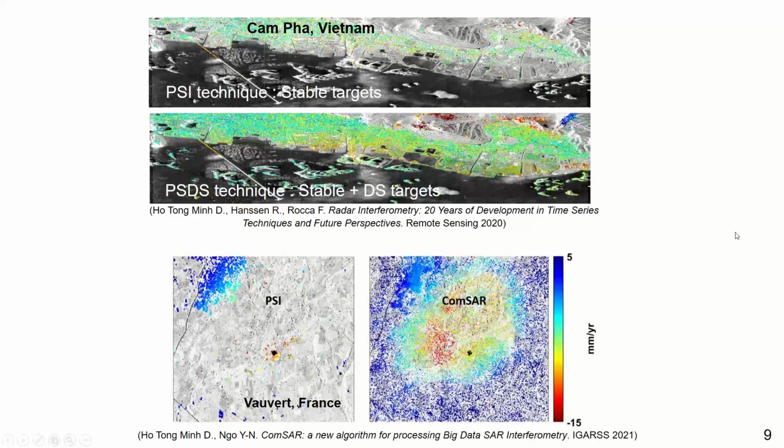And going to another test site, on your left, we can see this one is Beauvais in the south of France. The phenomenon over there is salt mining industry exploitation. When they do the exploitation, they have to inject water and pump the water at high pressure into the wells, to dissolve the salt layer at depth, and in that case they can extract the brine. That brine will be used for the chemical industry. This phenomenon has been happening for 30 years, and it induces subsidence of the surface.